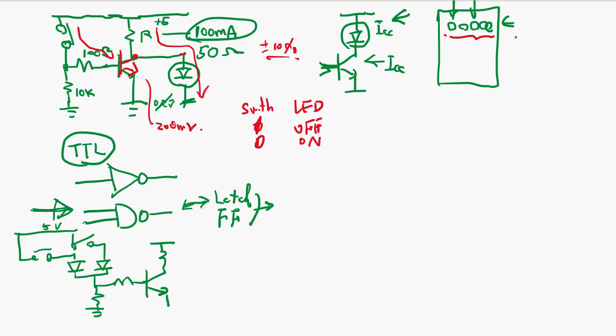Okay, so what I did is, if one switch is on, this is going to be pulled up, right? And the reason why I use a diode is that when this voltage gets high, it doesn't affect this side, okay? So it's isolated. So the two inputs are isolated. If one of them is on, then this is going to be off.